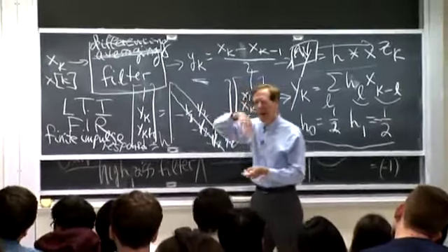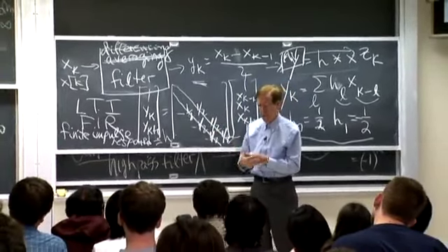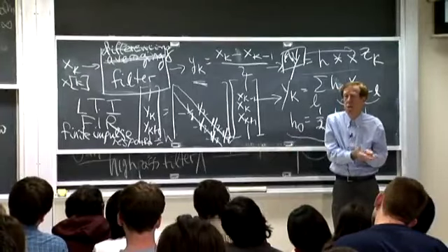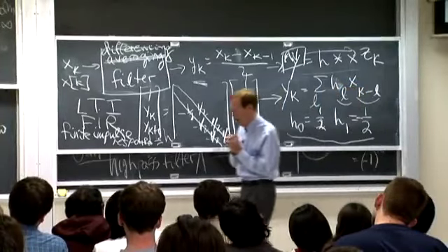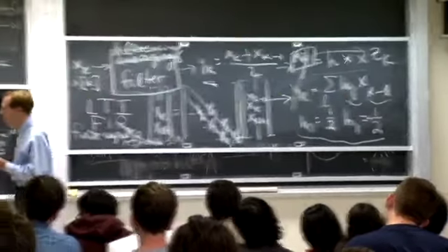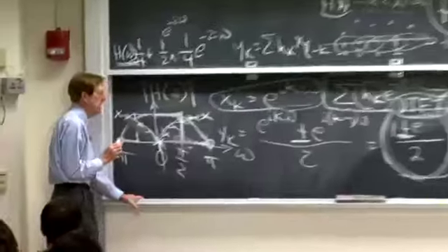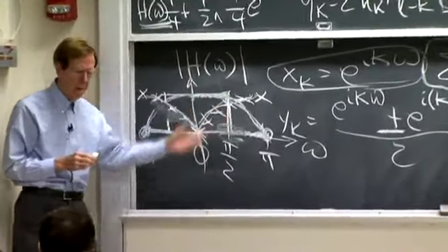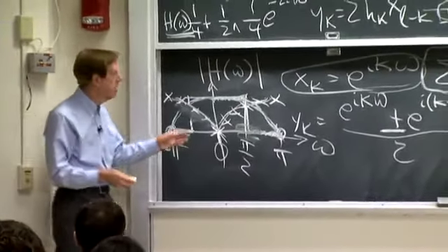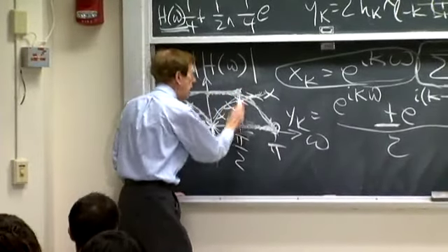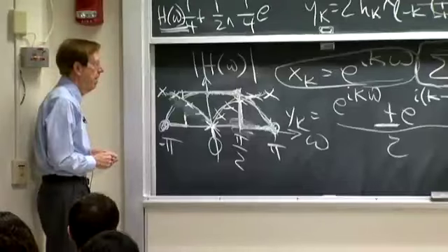Each time I did that averaging, I damped the high frequencies. So if I do it twice, I get more damping. But I lose signal, of course. I mean, presumably there's some information in the signal in these frequencies, and I'm reducing it. And if I average twice, I'm reducing it further. So a better one would be to get a sharp cutoff, yeah. Okay.